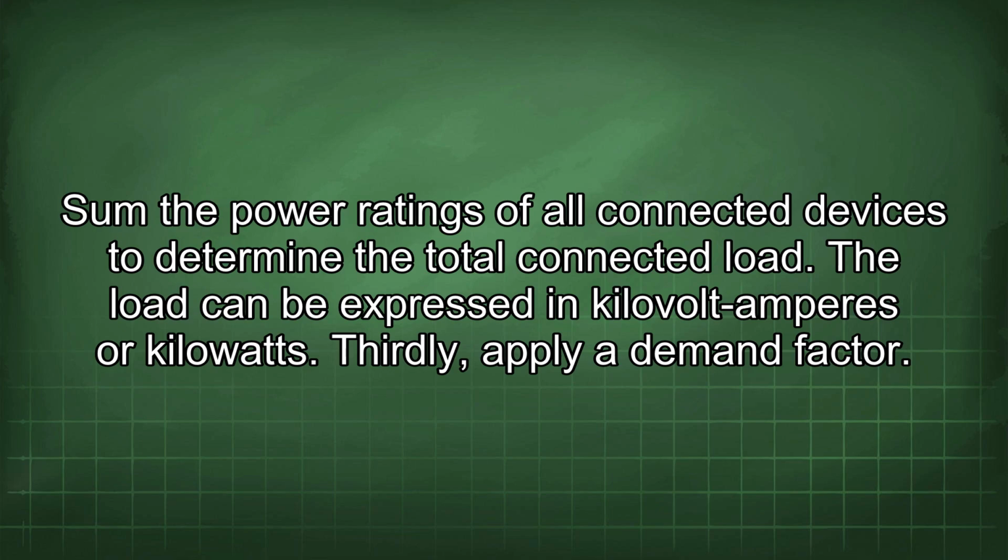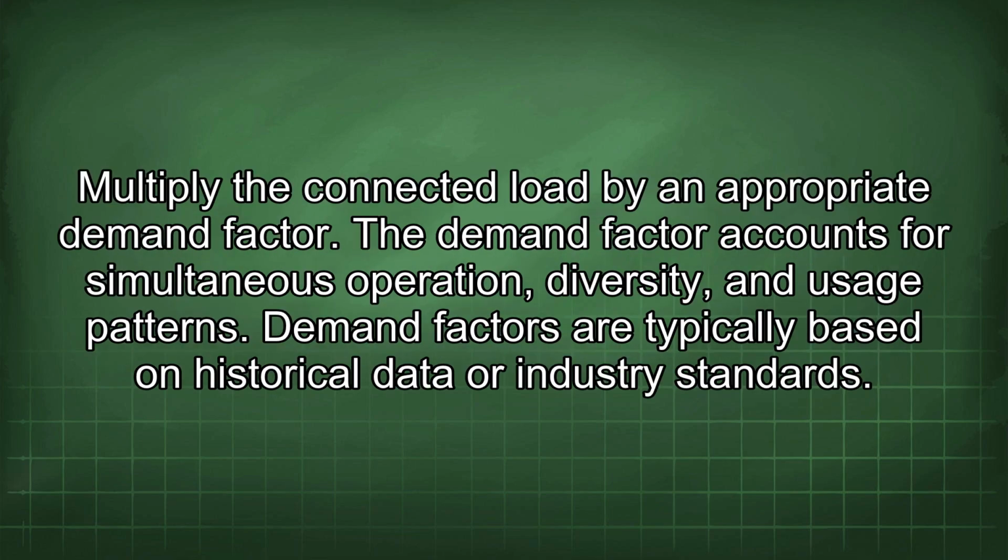Thirdly, apply a demand factor. Multiply the connected load by an appropriate demand factor. The demand factor accounts for simultaneous operation, diversity, and usage patterns. Demand factors are typically based on historical data or industry standards.